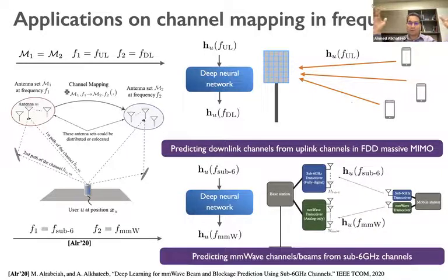So instead of, let's say in 5G NR, having maybe 64 SSB synchronization beams that the base station uses for the initial sounding, we can use this machine learning model to predict the best 4-8 beams that could be used. So I think a factor of 10 would be very reasonable in a way that is transparent to the communication system and to the standard. I have seen other researchers claiming more than this, but I think in the range of 10 is very reasonable with a transparent approach.